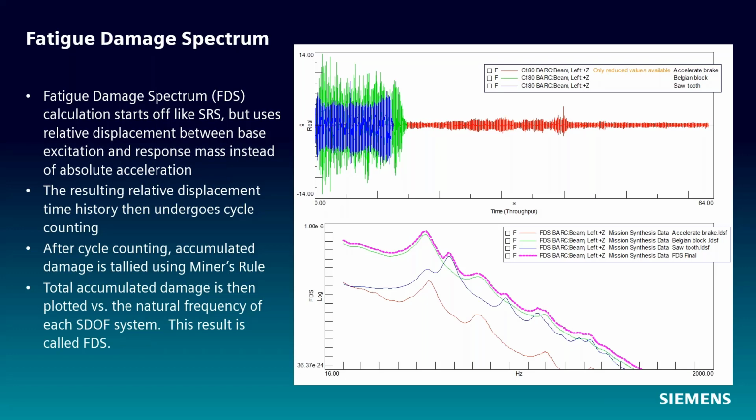So at the end of the day, you could run a random vibration control test to try and hit that magenta line? That's correct. This is a way for you to get vibration inputs from a number of different environments and combine them into a single environment to perform a vibration test so that your article under test, or your DUT, will survive those vibration environments.